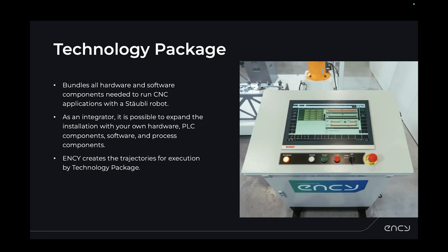The programming of the trajectories is all an offline process, which is of course great because you're avoiding machine standstill. But as Andrew already explained, this has one big disadvantage: whenever something changes on the real machine, the operator always has to get back to the programmer who made the program.